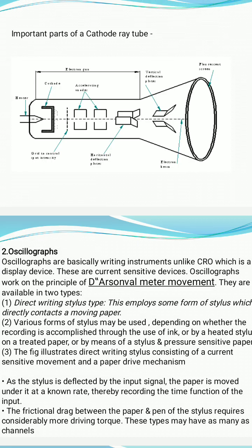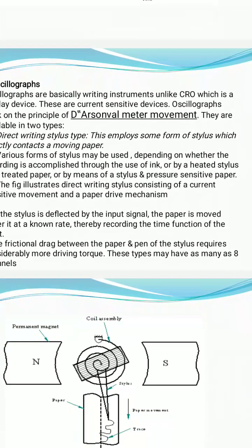It is called an XY plotter because it has two beams, one for the x-axis, other for the y-axis, and these two beams will move depending upon the signal supplied from the primary transducer. The output signal helps the beams to move in different directions, and the pen plots the graph or the image in the form of the output signal.